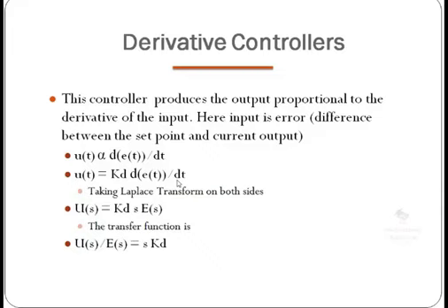What is the error? 100 is my aim, but it is settled at 60 degrees. So 40 is my error. It is saturated. In our words, dE by dt means what? Can you claim this as rate of change of error? Can you accept that the derivative of error is nothing but rate of change? Yes, sir. Rate of change is nothing but derivative.